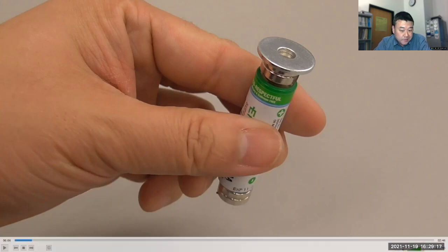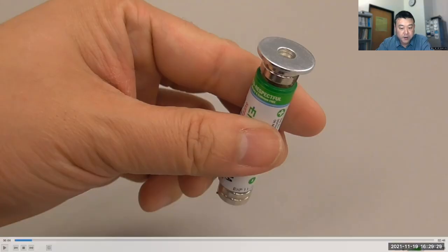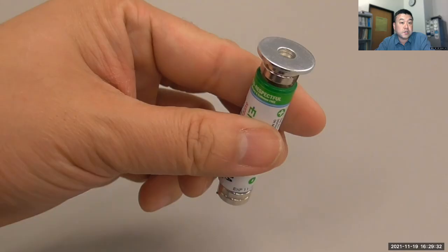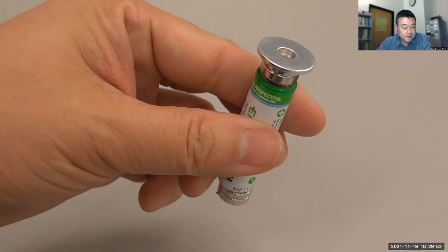I just wanted to put both, because these magnets are actually playing one more role in this demo. They also serve as a conductor. The coating around the neodymium magnet is electrically conducting. So the magnet stuck at the bottom basically provides a surface for electrical contact. And this washer up here is not necessary for any electrical or magnetic reason. It's necessary for a mechanical reason. I'm going to place the wire in this well so that it doesn't fall out as easily. So that's the whole setup.